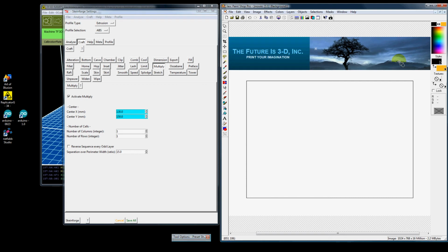My name is Jeff Christiana and this is video number 19 of the Skeinforge 47 video series on how to use multiply. On the screen we're in Skeinforge. We're on the multiply tab. For our printers, you want to activate multiply, because when you start a print job, our printers auto home to the lower left. If you do not check activate multiply and you don't put in coordinates of your center, your part will print in the lower left of the screen.